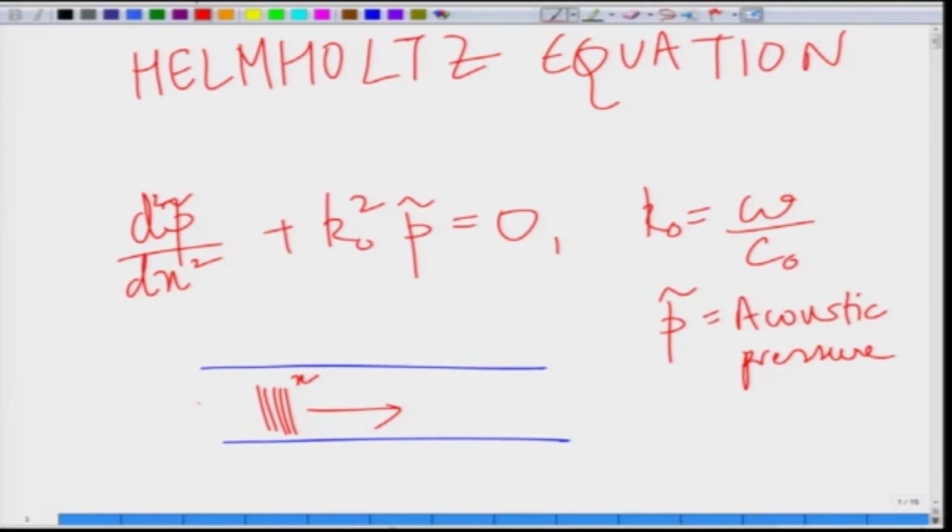Of course, other waves propagate in this direction, but the idea is that if we consider the duct section to be circular, it could also be rectangular or square, over this entire section the acoustic pressure value is constant, and so is the acoustic particle velocity along this direction. So, the phase of the wave is constant over this plane, so it is also called planar wave fronts.